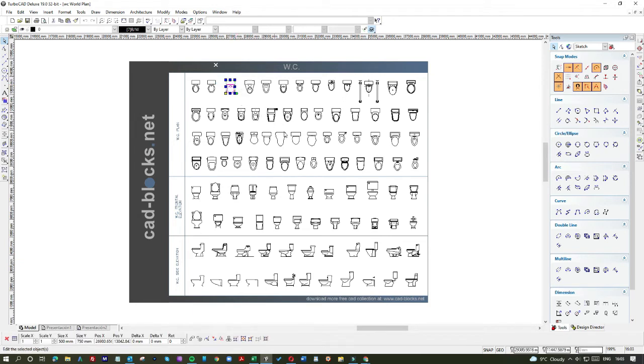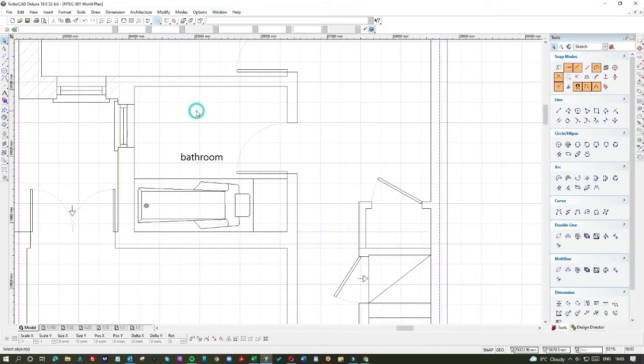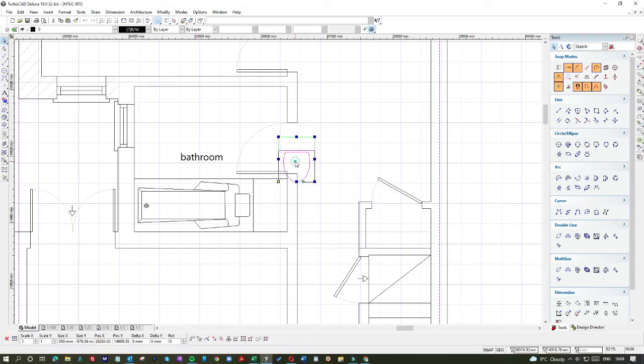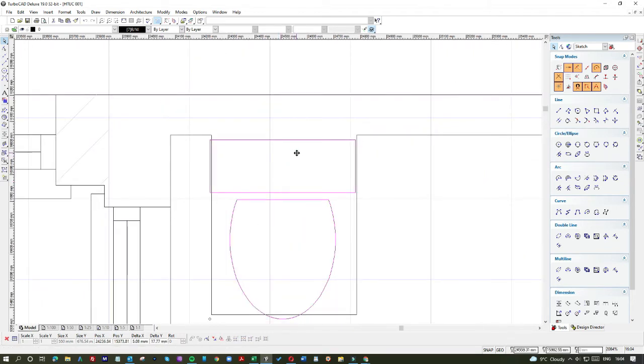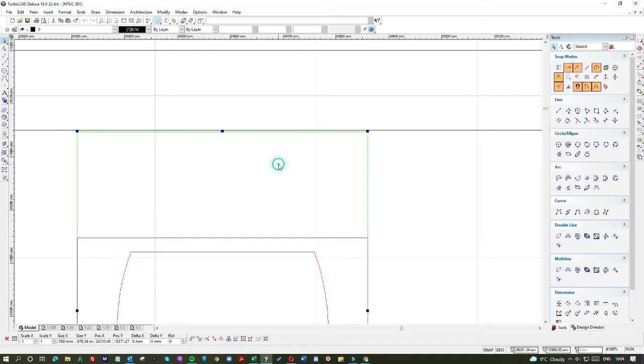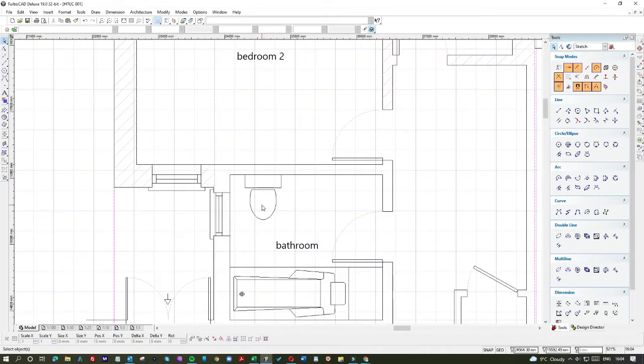I used this one quite a bit, but we could do something a little bit different today. How about keeping it simple again? Looks like it has a seat down on it, which is always good. Again, to scale, that's about right, 670, 550. You can get different size loos. Sometimes if the space is restricted, you can get a smaller loo, which are about 450 wide and about 600 in depth. So here we've got all the space we need, so we can be a little bit generous.